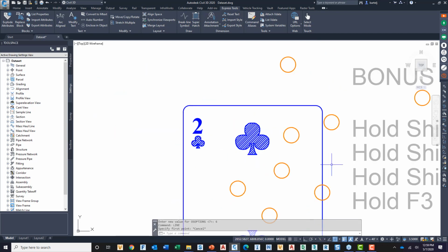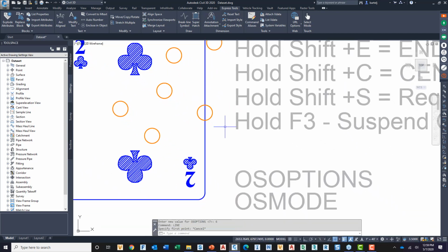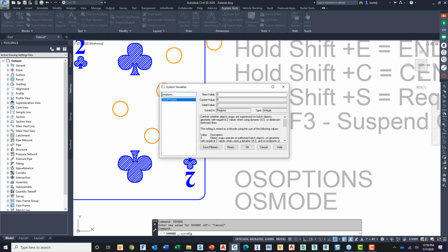All right, last and final thing, I showed you how to make a script file. You specify the different values that you want. All of the values for your settings are set up in a value that's called Osnap mode, much the same way we looked at before. Any object snap that you have, we'll say OS mode, it's got a bit code associated with it.